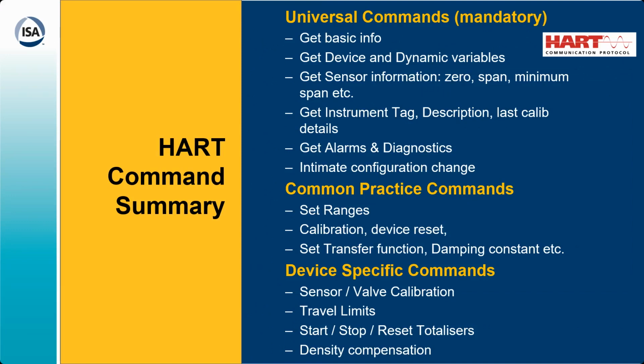Plus, you get all the sensor information of your sensor, instrument tag, description, everything which is required for instrument management, alarms and diagnostics, all those things. And apart from that, if somebody changes some configuration in the device, you get a configuration alert so that you can call up that command and you can upload the configuration onto the cloud or onto your host systems. Different common practice commands for setting the ranges and calibrations and device reset are also possible.